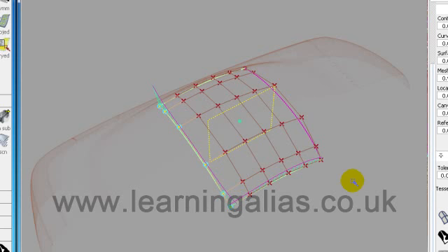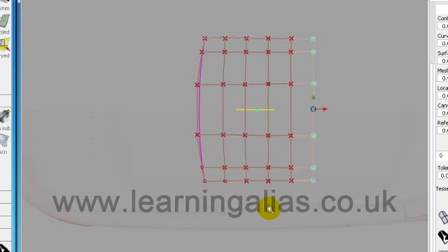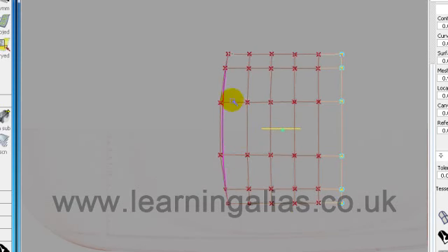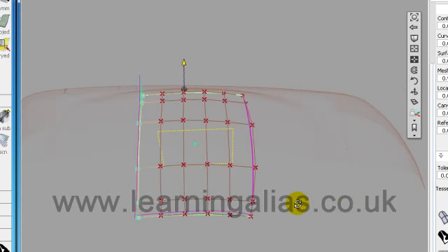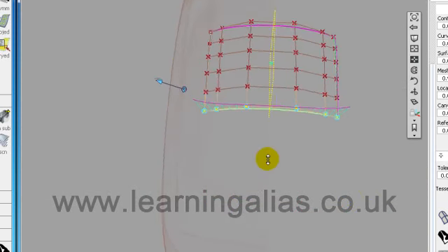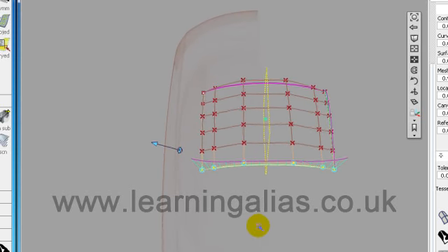As you become more experienced at Alias, you may want to develop this curve here to make it more compatible with the blend. And you see I've got one straight edge there in top, and I've got one curved. But if you want to develop a slightly curved edge to promote a better blend and better highlights, then you can do that with the Planarize CV tool by just changing the angle.